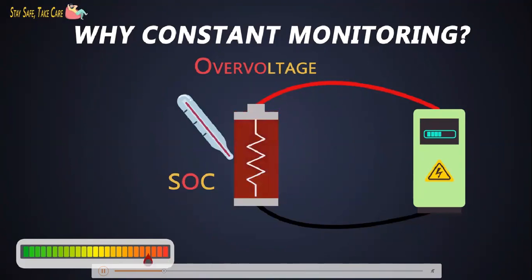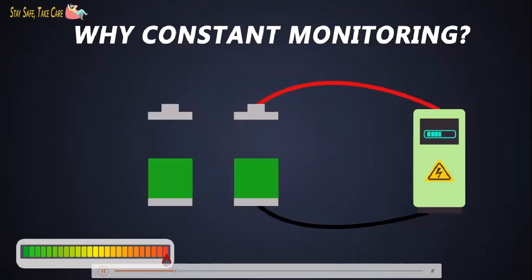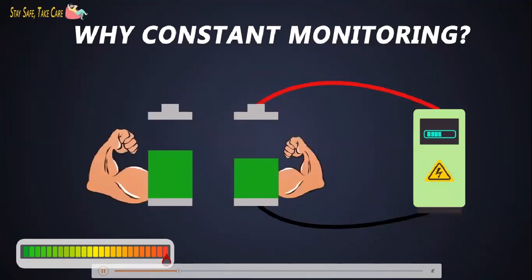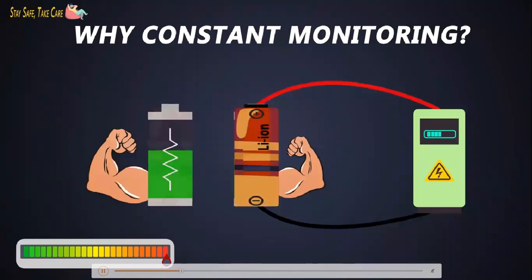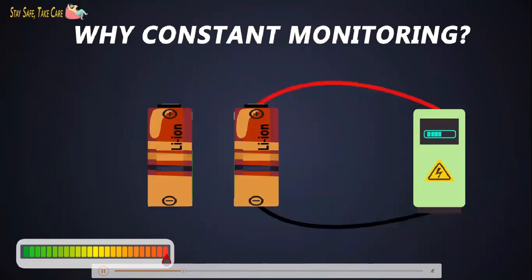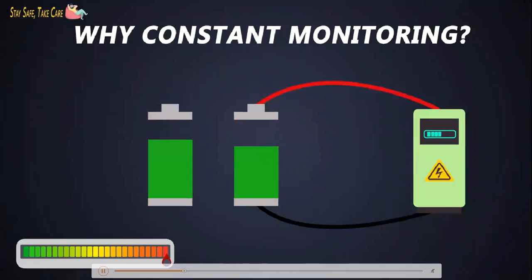On the other hand, if the voltage applied to the battery is lower than the limit, it also leads to over temperature. Over voltage and under voltage lead to a temperature which degrades the battery life, and if we use the battery at a temperature lower than its specific range, then its capacity decreases. Due to over temperature, the batteries might catch fire.